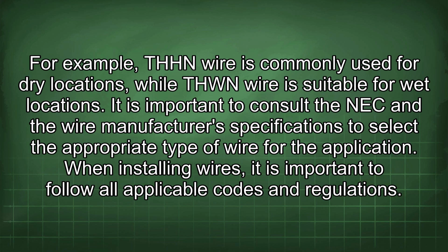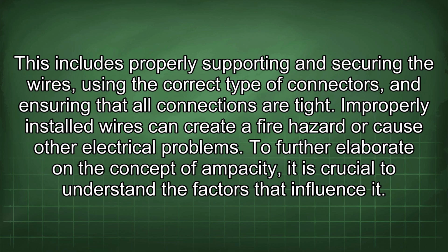When installing wires, it is important to follow all applicable codes and regulations. This includes properly supporting and securing the wires, using the correct type of connectors, and ensuring that all connections are tight. Improperly installed wires can create a fire hazard or cause other electrical problems.